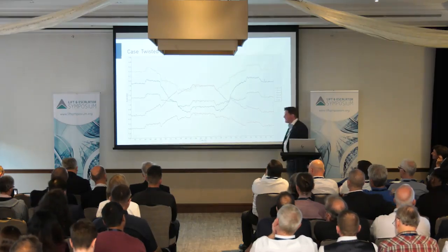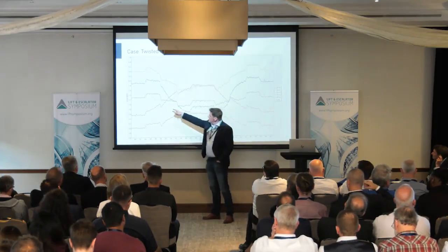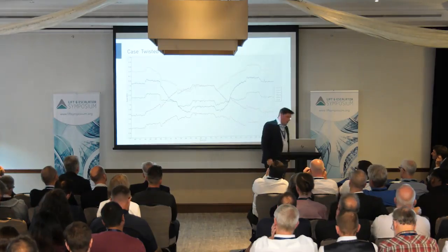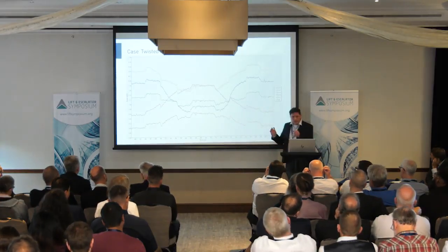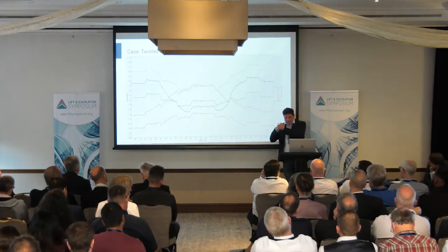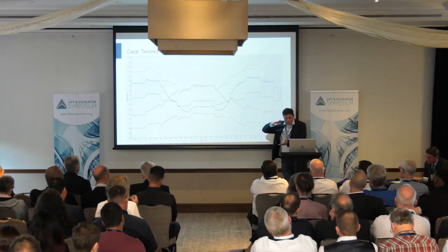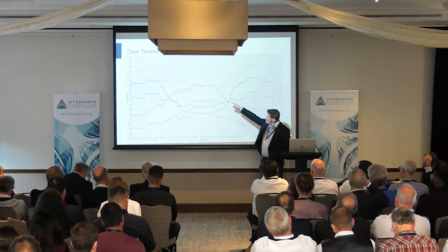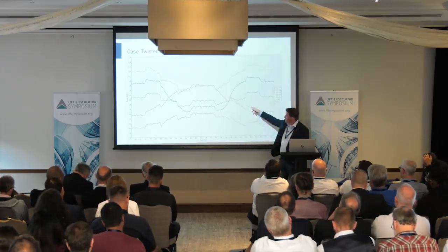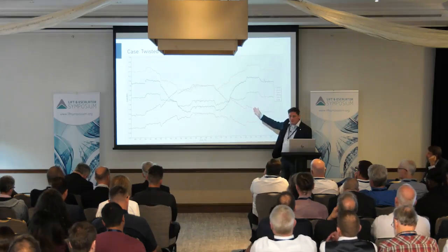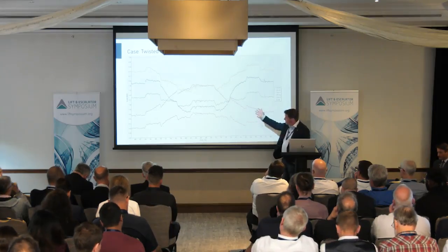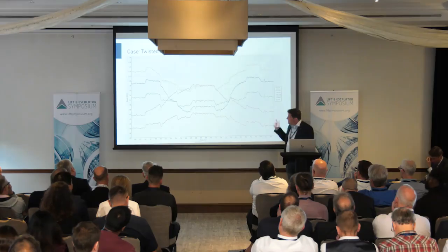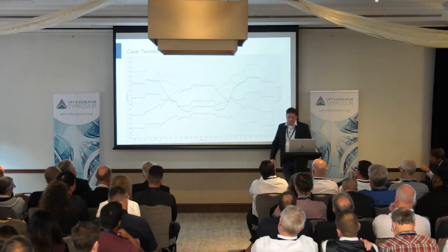And you can clearly recognize this rope by just looking for the rope which is increasing over the travel in an up direction. So what is happening with the rope in up direction if it is twisted? It is twisting more and more. The distance to the traction sheave becomes shorter. And as soon as it travels in down direction, it does the opposite, but exactly the opposite. And yeah, you can do 100 of these travels and they will all look the same. So it is also more or less easy to detect twisted ropes from such a measurement.